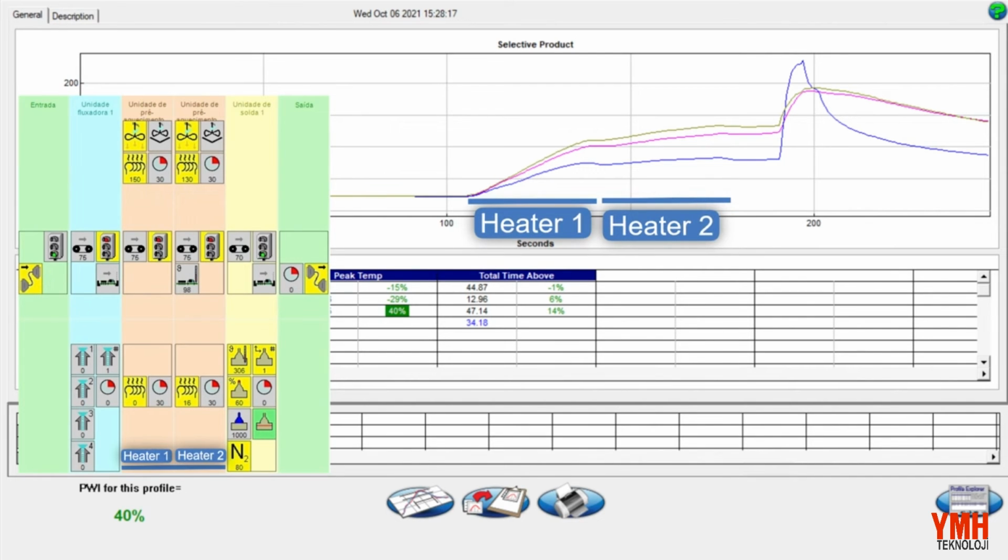In the selective solder machine example, it's possible to modify the temperature set point, the time the board pallets stop in the two preheating zones, and other set points. The modification of the set points will create an impact in the time duration that the board is heated up on each preheat zone, as well as the ratio of heat transfer to the board. Increase or decrease set points accordingly with your optimization goals.